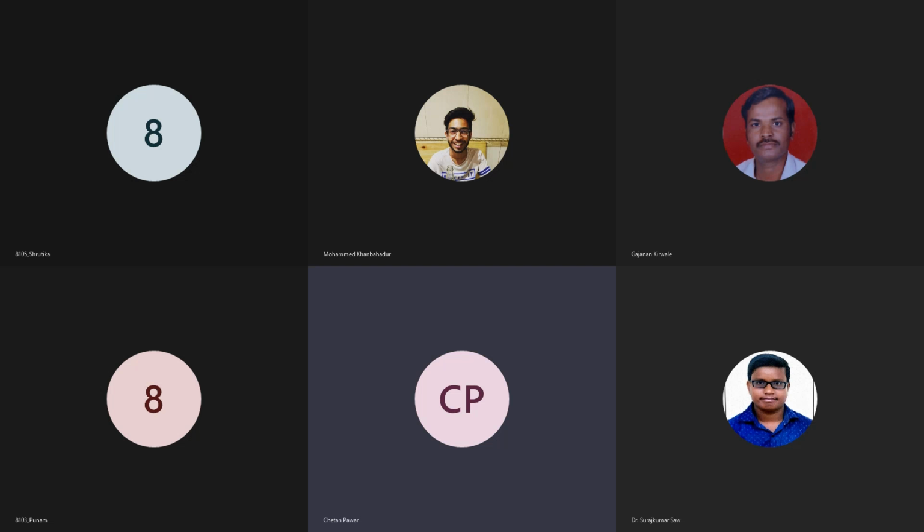Shrutika, one thing I want to tell you: don't connect the VDD directly here. You just put a supply voltage, delete it. Take one supply, just copy it. No, don't copy. You have to paste one VDC source. Now you take ground and connect it. Here you put the voltage source as VDC equal to 1. Now it is okay.